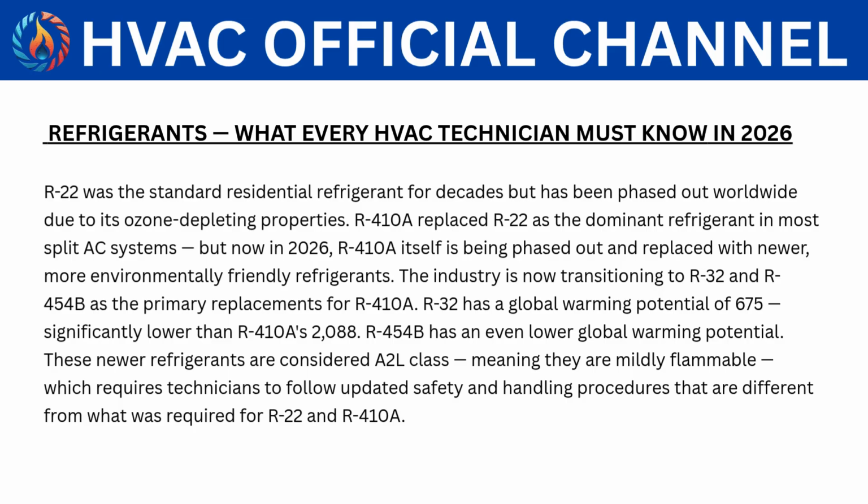R22 was the standard residential refrigerant for decades, but has been phased out worldwide due to its ozone-depleting properties. R410A replaced R22 as the dominant refrigerant in most split AC systems. But now, in 2026, R410A itself is being phased out and replaced with newer, more environmentally friendly refrigerants. The industry is now transitioning to R32 and R454B as the primary replacements for R410A.